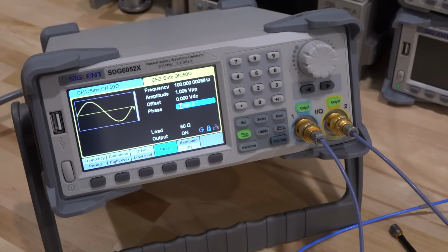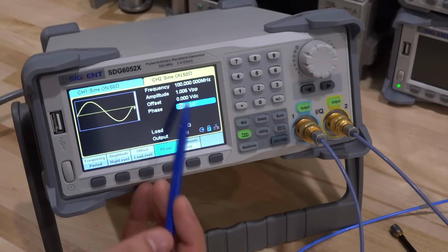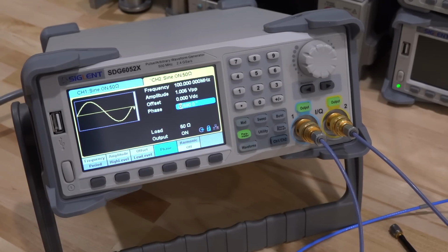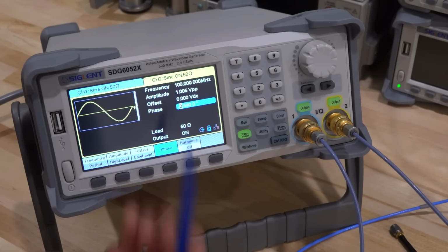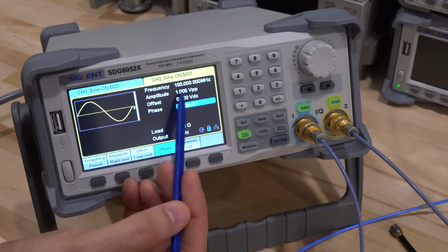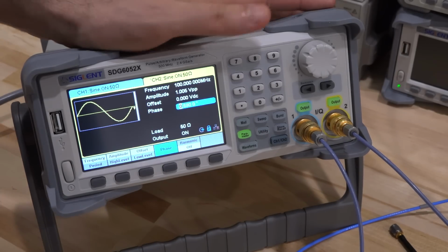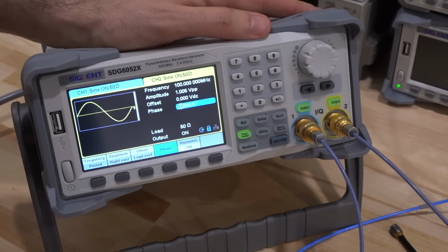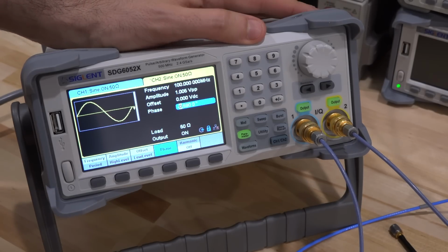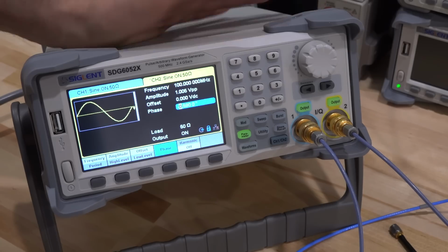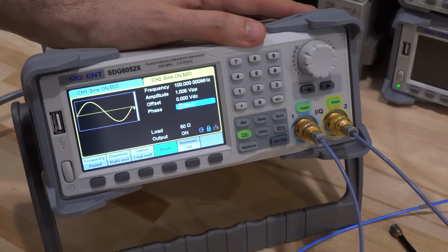The hybrid is supposed to be sub 1 degree at 100 megahertz, and it is sub 1 degree offset, and it's supposed to be very good in amplitude matching, and indeed it is. Keeping in mind that this 1.005 has some discrete steps associated with it when we're comparing them. So you can see you can indeed use this instrument's very nice phase locking and amplitude accuracy of the two channels to do fairly sensitive measurements and get reasonable numbers from it. So I'm happy with that.